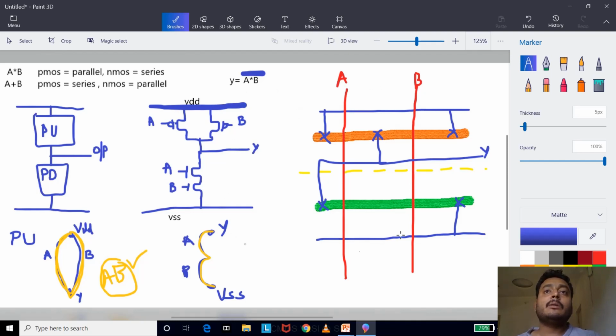Okay. So this is about how to draw Euler's graph and draw the stick diagram for it. You can see you are not keeping this connection, right? A and B are joined together already, so you don't need to make any connections from your side. These are the intermediate connections you have to check. You can also observe that I am crossing metal lines over the polysilicon. These two are different layers, so even though I'm crossing here, there is no electrical contact. Where this is the substrate layer and I'm using metal, I indicate the contact, because these are different layers and there is a contact present there. Okay, we'll go back to your slide.